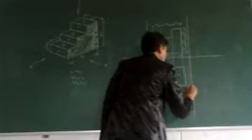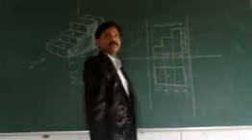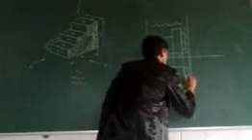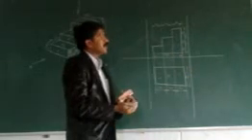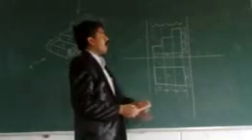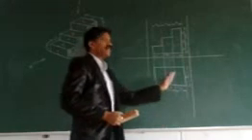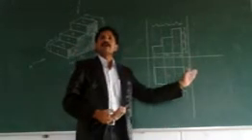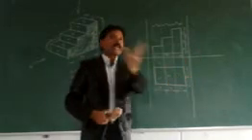And coming to the width, here I am going to tell one more method: how to transfer the width onto the side. See here, this dimension is 50, the width is 50. Getting the side view is very, very simple. The height is already projecting from the front view, and the width we are going to transfer by means of the radius method or the angle method.